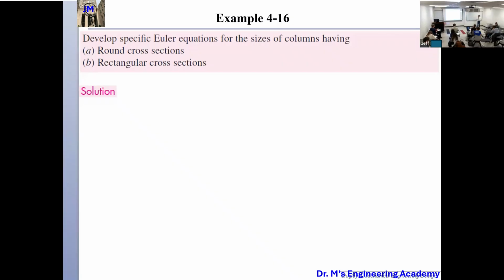What does it say? It says that if you know the case scenario, the ending condition, Young's modulus, and the length, then given a load, I can use this equation to calculate the D, right? Our course is called machine design. Machine design means that you give me a load and Young's modulus, and I give you the structure that satisfies your needs. So with the load, length, Young's modulus, and case scenario, I can use this equation to design a column with the appropriate diameter.